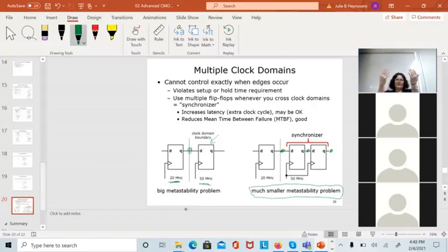And then they go to DDR2, so now they're getting 4 data bits out every clock cycle. So if you're using the delay lock loop, it helps: if it was a 100 nanosecond clock period, they have 1 clock that goes off at 0 at the clock edge, 1 clock that goes off 25 nanoseconds later, 50, and 75, and then rely on the system clock to do that.